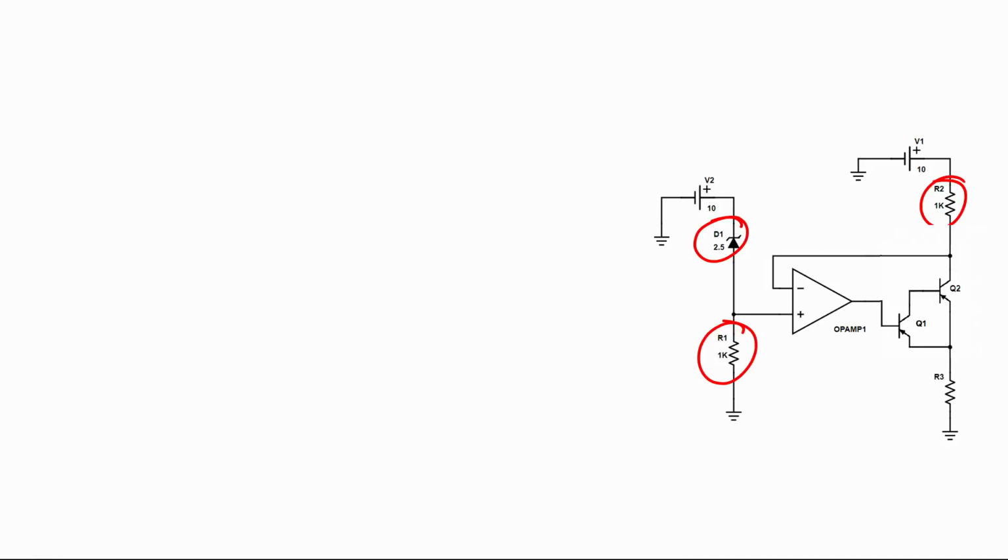Now, if you recall the working of a Zener diode, it is generally worked in a reverse bias condition. When we see the cutoff value, they have mentioned it as 2.5. That means that in reality, no matter what voltage you apply as an input to the system, and since this is completely in a reverse bias condition, the drop across the Zener diode will always be 2.5 volts. So the drop across the Zener diode is 2.5, good.